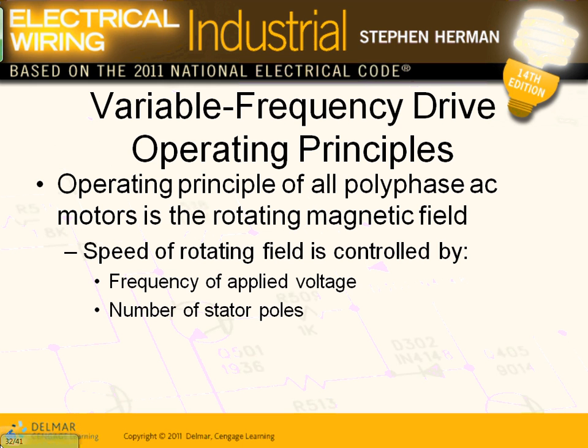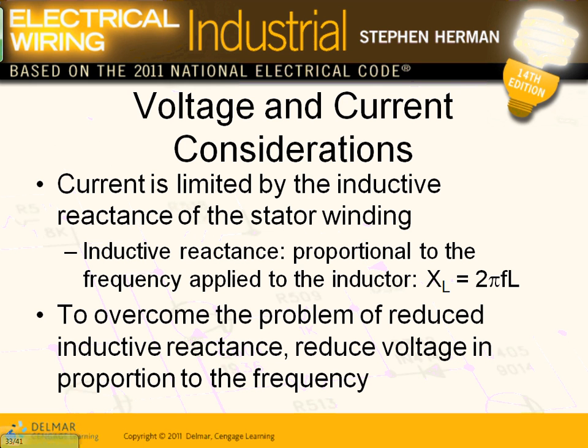So to control the speed of a motor, guys, we can change the poles. That's the old-fashioned way of controlling the speed. The new-fashioned way right now is controlling the frequency and the voltage. The frequency and the voltage. So we have the induction reactance. So what this says, guys, in an AC motor, take this.